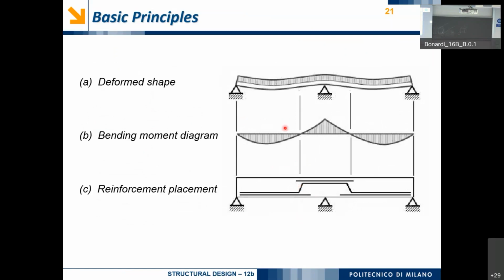So the bending moment is drawn like this, not just for fun, because we want some reference. When it is positive, we draw it downward, and if it is negative, we draw it upwards. It's not a meaningless reference, but a significant one, because we usually draw the bending moment diagrams on the side where we have tensile stress.